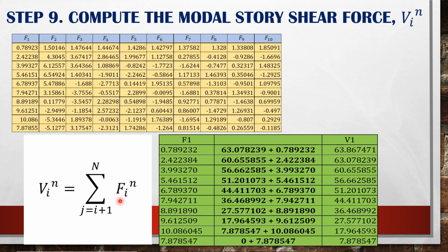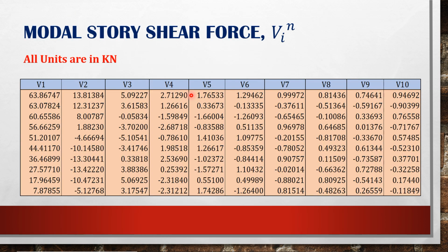By using this method, this process, and this formula, these given values, we can solve for our modal story shear force in the first to 10th floor in all modes. So if we use this formula in the process presented, we can determine the modal story shear force in all modes and floors. So this is our modal story shear force.